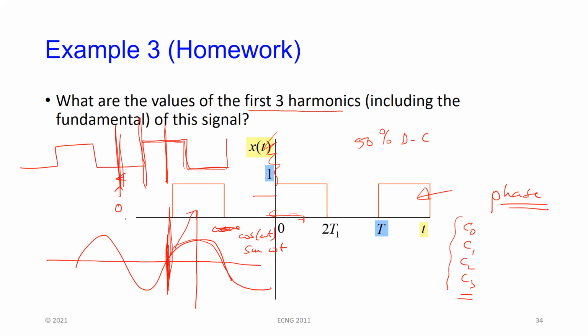But you know that cosine is just sine omega t plus pi over 2. In other words, that phase angle has come in, right? If I looked at it here, that is minus cosine. So there's a sine plus a pi phase angle. So the same thing is going to happen here when you look at it. You're going to get the same components, but that phase is going to come in inside of there and play.